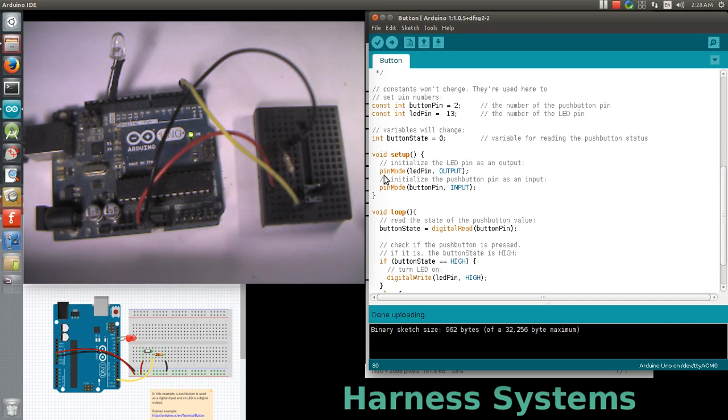In setup we do all critical hardware initialization for our application. Here our application is to toggle LED based on the status of the input switch. Push button is set to input port direction and LED is set to output port direction.